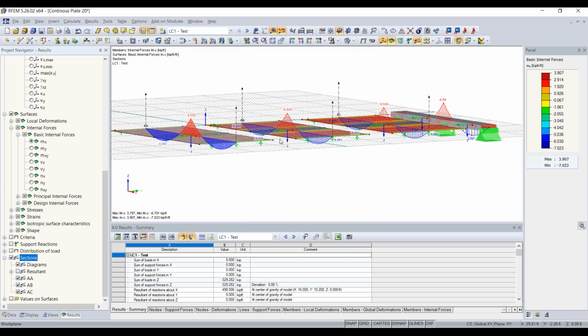And maybe now you can also see the difference in accuracy between our plates here, depending on the FE mesh size we chose. So this first one was 0.2, and then we increased the length between all of them. So that's showing you how the results and accuracy can change.